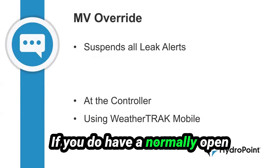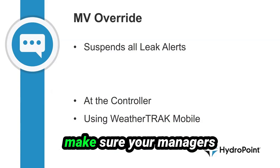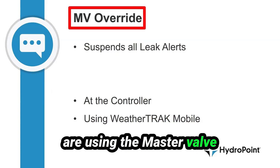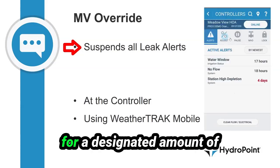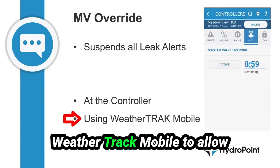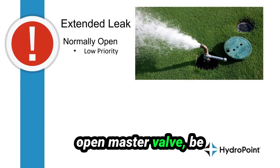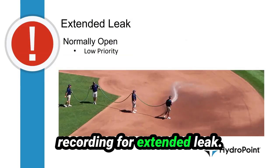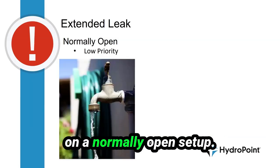If you do have a normally open master valve and you want to manage the number of leak alerts that you're receiving, make sure your managers are using the master valve override feature, which is a countdown feature that suspends all leak alerts for a designated amount of time and can be set either at the controller or using WeatherTrack Mobile to allow for routine maintenance. If you are using a normally open master valve, be sure to check out the recording for extended leak to fully understand the WeatherTrack leak response on a normally open setup.